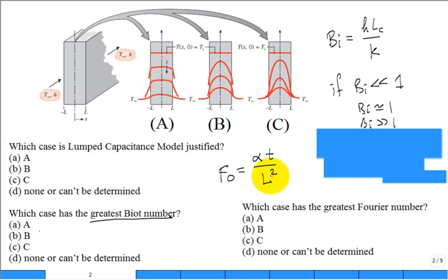All right, we'll go ahead and stop and we'll talk about it for a minute. Well, I forgot, Professor. What is alpha? Thermal diffusivity, k divided by rho c. It's just a property like k, just like rho, just like c. I can get the thermal diffusivity of the material of interest. What is L? Some length, right? So what is t in this equation?